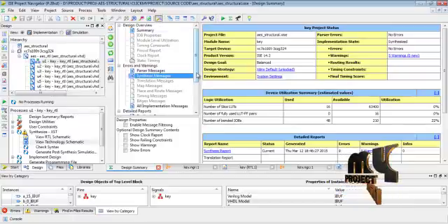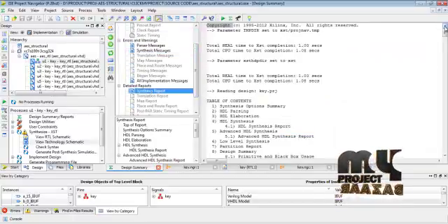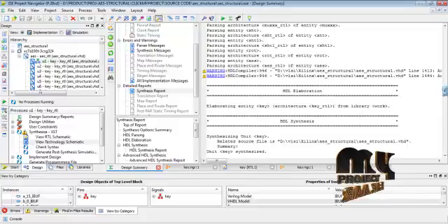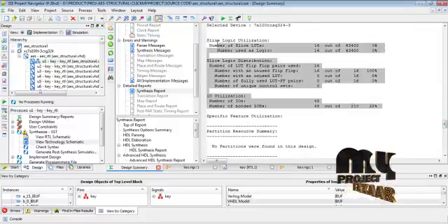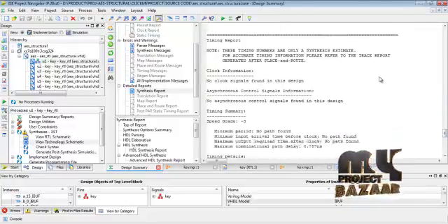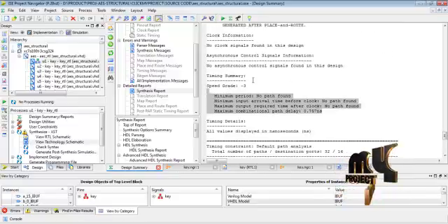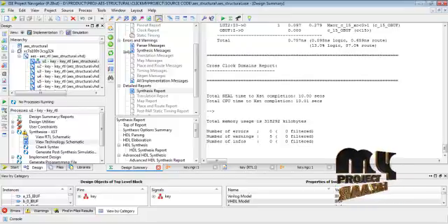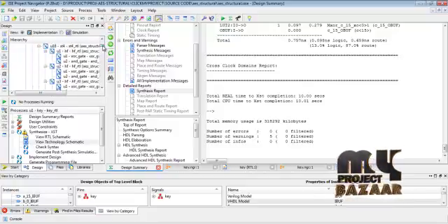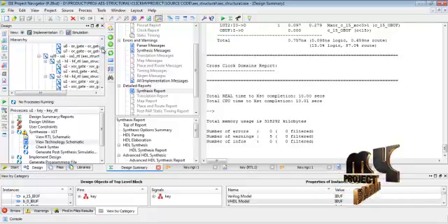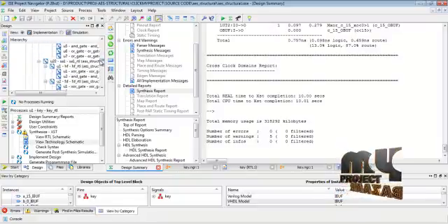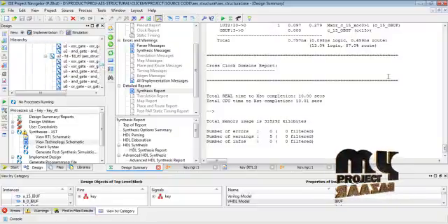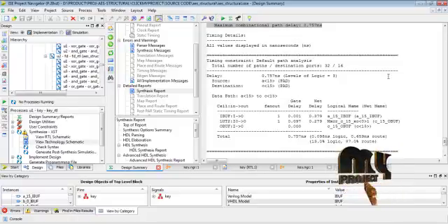Then go to the design summary process. The design summary process selects the synthesis report result. The report results are mainly used to calculate the area in the overall architecture results and to calculate the processing time for the overall calculation of the AES architecture process. This is the sample for key functions, calculating the overall sub-bytes, mix columns and shift rows separate synthesis report results, and combining the overall AES architecture results for our final 128-bit AES architecture.